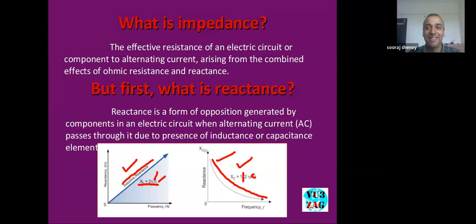Okay, I'll take this point as an improvement suggestion. Thank you for that. Yes, it can be doable. In this case, I kept this as a minimalistic design, so only a single LED is used, which is directly connected to an SWR bridge. It is possible to have multiple LEDs, like level indication and all. For that, we need to add some additional circuitry, such as an op-amp measuring the reference voltage and then indicating the LED accordingly.